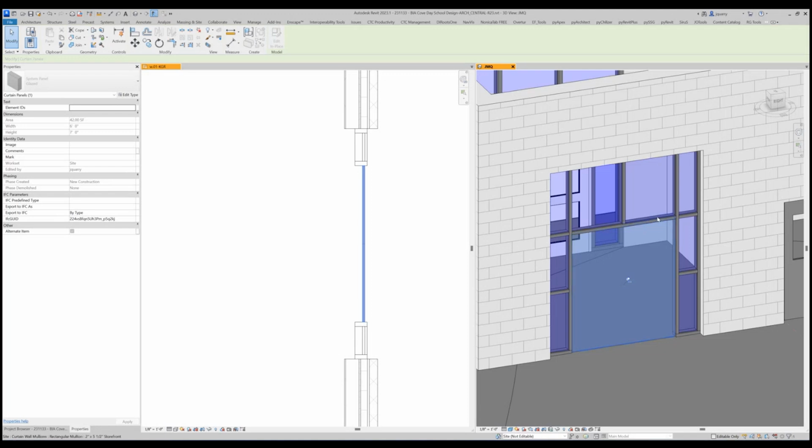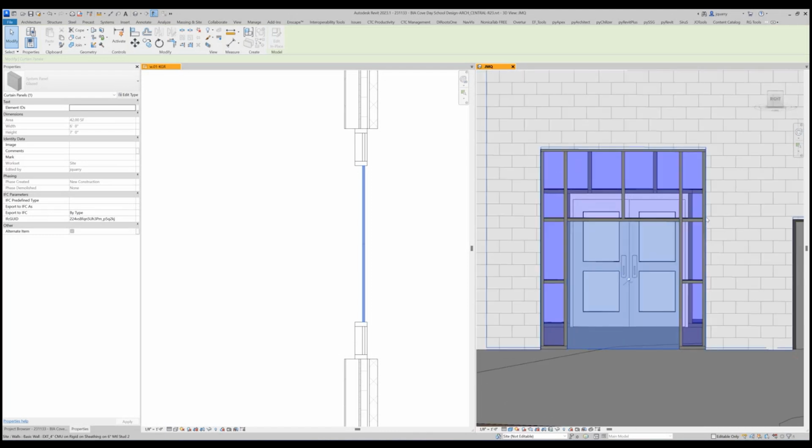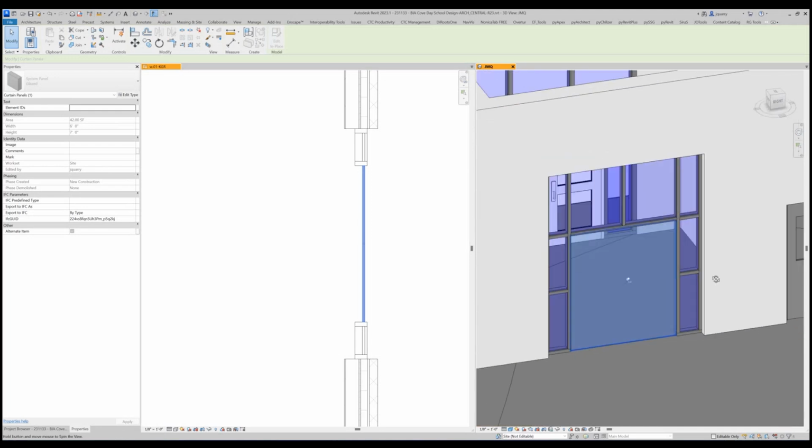All right, and I would assume that we'd want our mullion heads to align with that, across our elevations. Yep, with your masonry dimensions. So if you go to 7'4", it's going to line up with that guy. Yeah, exactly. Yep, perfect.